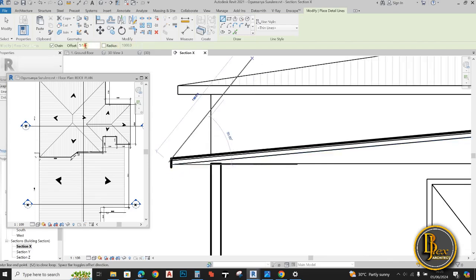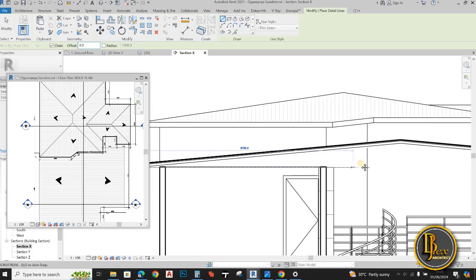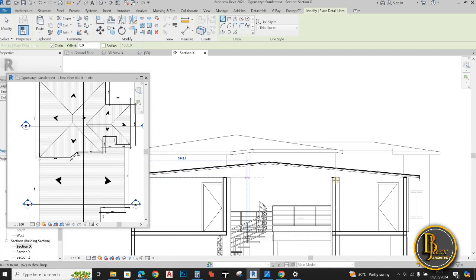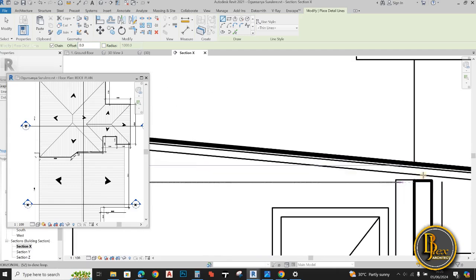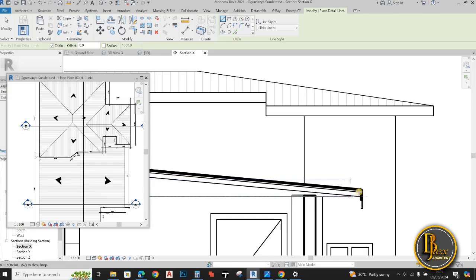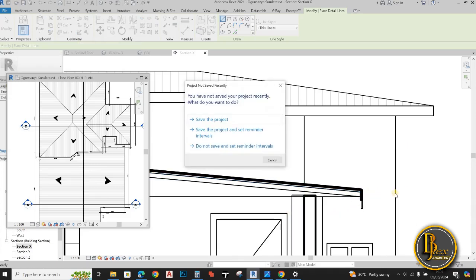So basically, this section is not measured. But if you are to do your sections, I believe your measurements for your king post and your rafters would be in your detail works. For this one, we'll be using a rough estimate of 50 millimeters for our tie beam. So I'll be using thin lines to draw the tie beam.